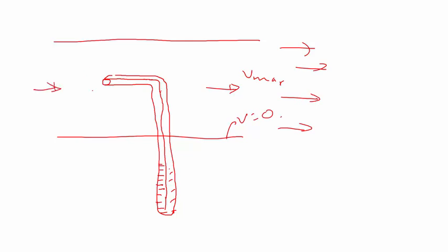So when the fluid goes this way, on this side of the tube, fluid enters through this hole, goes this way, and pressurizes this manometer fluid. On the other hand, the fluid that goes over that tube still has the velocity, and then right here there is also pressure that goes this way, which is basically the static pressure, because on this surface the velocity again is 0. So on this hole, on this side, it will only read the static pressure. And on this side, I have both the dynamic pressure plus the static pressure.